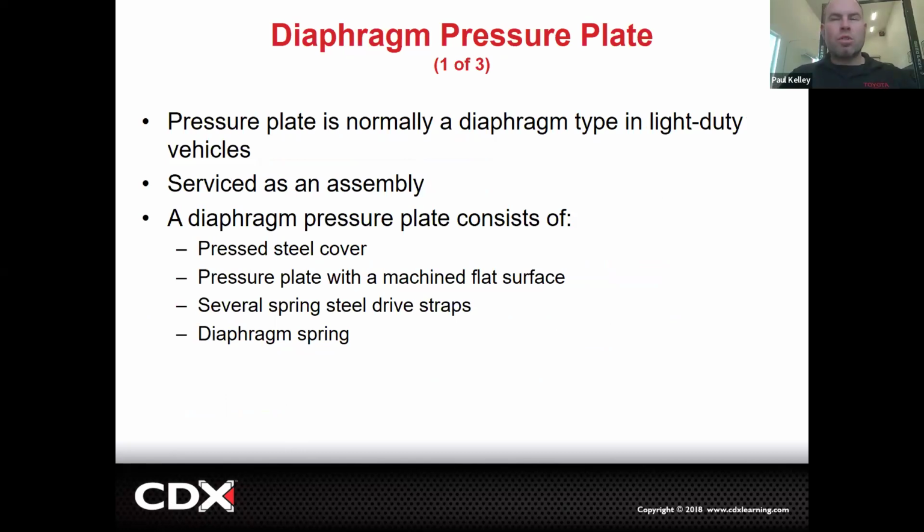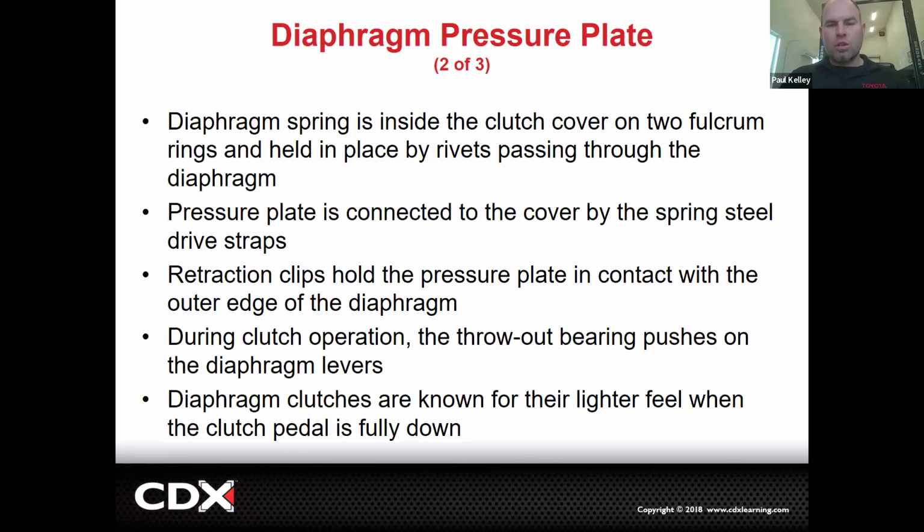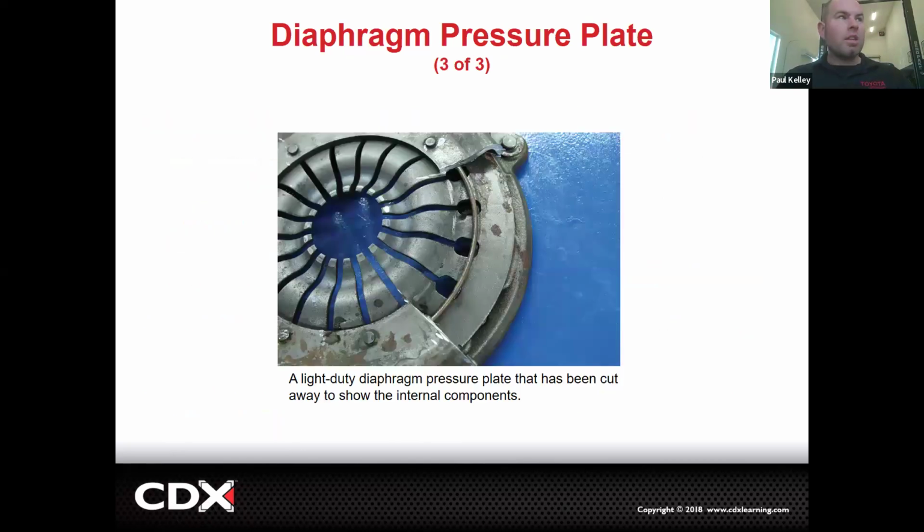And by the way, if you don't know what type of clutch cover spring it has, it's not a real big deal. Just want you to be able to know that they do vary. So there's a really good one of the diaphragm springs. Sometimes I've even called these the finger springs or something. But right here is where that release bearing sits. Remember, if we want to release those, that's my fingers. If we want to release my elbows, I need to push those down so my elbows will come up, right?